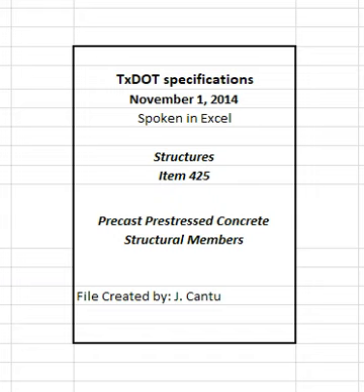Precast prestressed concrete bridge deck panels will not be paid for directly but will be subsidiary to pertinent items. Precast prestressed concrete piling will be paid for as specified in Item 409, Prestressed Concrete Piling. No additional compensation will be made for alternate designs or for any increase in quantities required to accommodate alternate designs, including quantities paid for under other items.